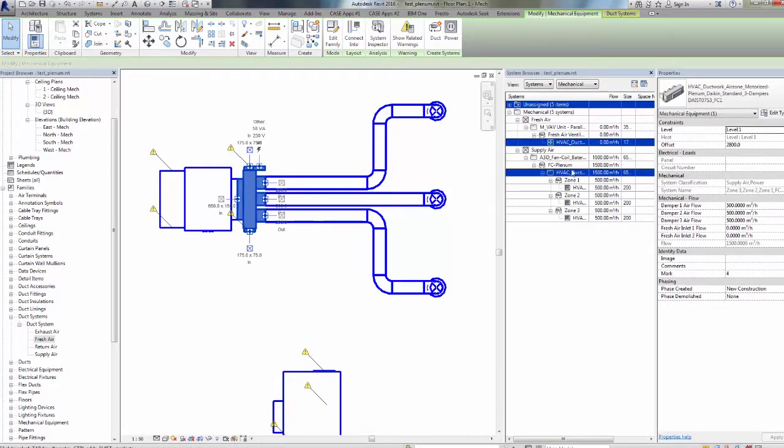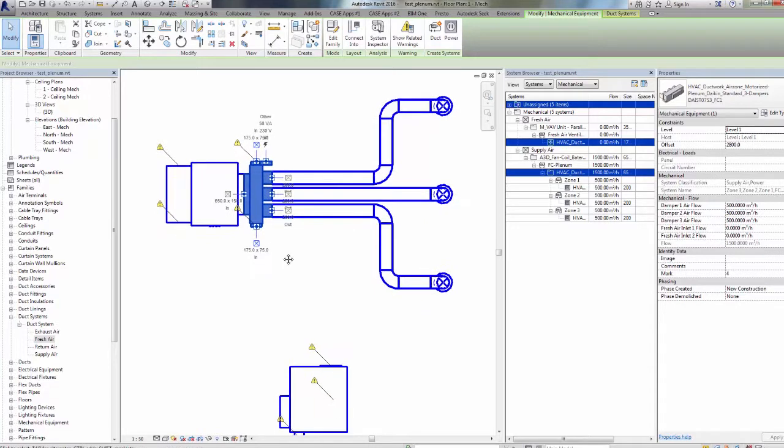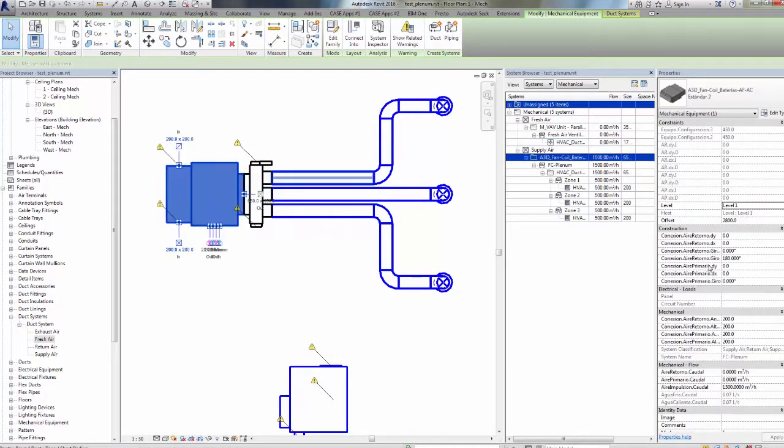By selecting the plenum both in the system browser and in the plenum itself, it is shown the global airflow, which is the result of adding the individual airflows from the outlets. We are now seeing how the fresh air is treated. We see that the global airflow in the indoor unit is the result of adding the individual airflows from its outlets.